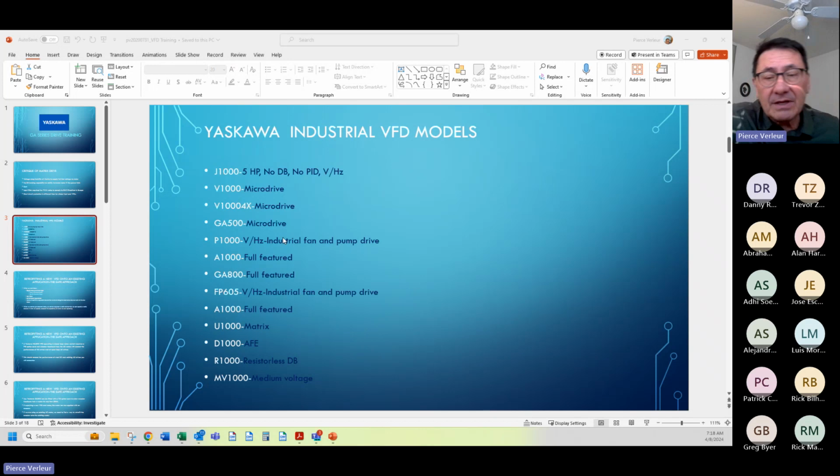And what's important about having a NEMA 4X product is that you give the customer the ability to put a disconnect on it at a minimum, if not a circuit breaker. Otherwise, he has to add another NEMA 4X enclosure out there next to your NEMA 4X enclosure. And some operators on the front that are not keypad oriented, like switches and a pot. That implementation was done very well by KB and several others. Unfortunately, the KB drive isn't very reliable, but their NEMA 4X implementation has been great. And I sent one to the factory saying, hey, we need to do it this way.